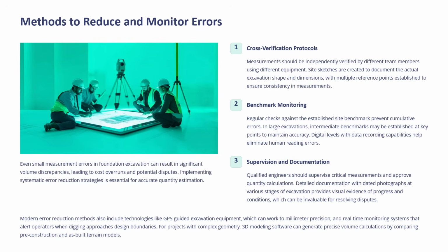Next is methods to reduce and monitor errors. You have to employ certain methods to reduce and monitor errors, because even if you have small measurement errors in foundation excavation calculations, it can result in significant volume discrepancies, which leads to cost overruns and potential disputes. So implementing systematic error reduction strategies is essential for accurate quantity estimation.